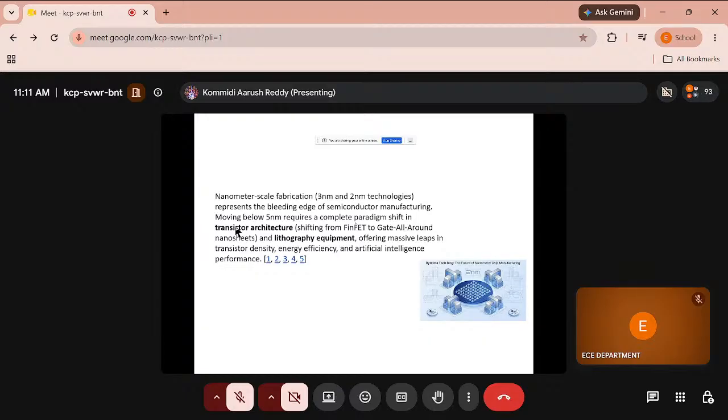Then you go for metallization and interconnections, and then reaching the higher Industry 5.0 technologies, consisting of nanometer scale fabrication, gate-all-around technologies, and FinFET technologies. These are all coming up to the market. These fabrication technologies play a very important role, which increases packaging density, improves performance, and reduces power consumption.